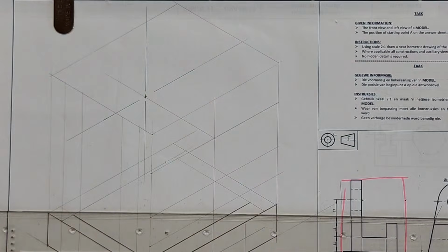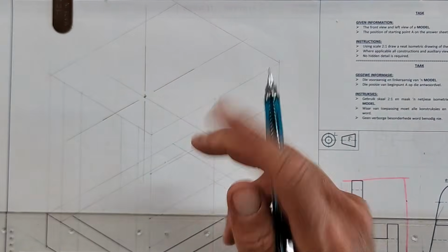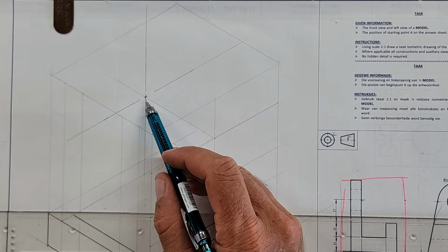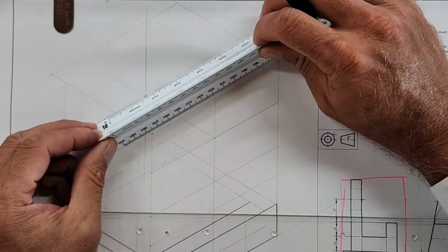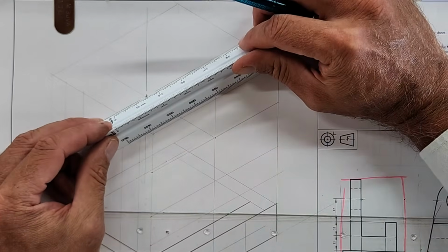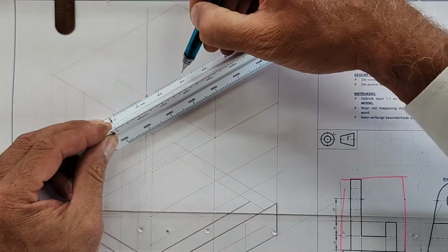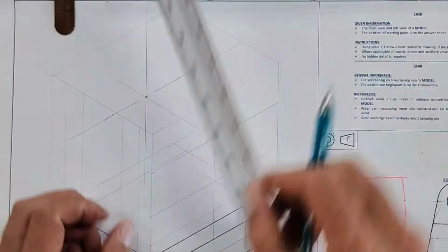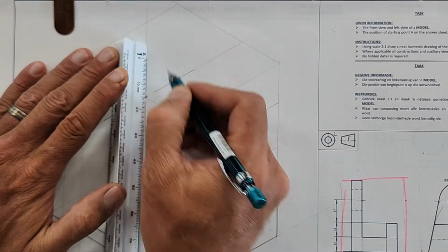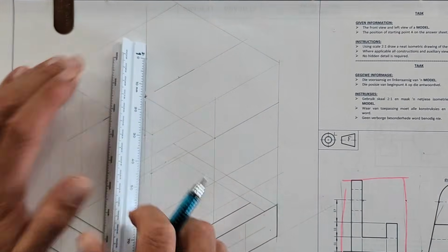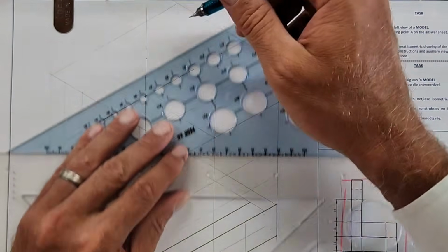Okay, can you remember how we do our symmetric circle? If this circle is a radius, everybody just quickly, do you understand how I got that center? Okay, so radius 15 means scale 2 to 1, 15 in all directions, this way, flip it, this way, this way, and I draw an isometric square.